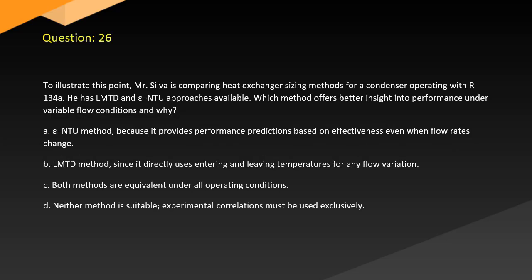Question 26. To illustrate this point, Mr. Silva is comparing heat exchanger sizing methods for a condenser operating with R134a, with LMTD and NTU approaches available. Which method offers better insight into performance under variable flow conditions and why? A. The NTU method, because it provides performance predictions based on effectiveness even when flow rates change.